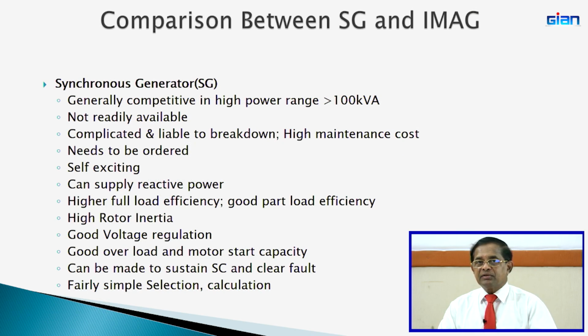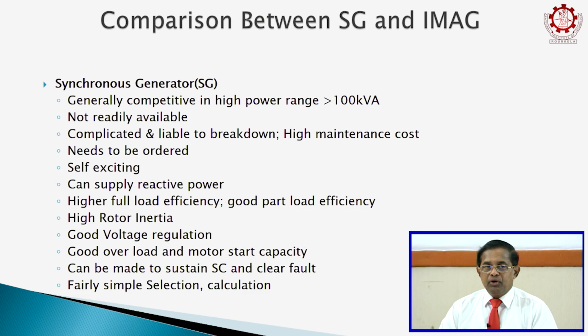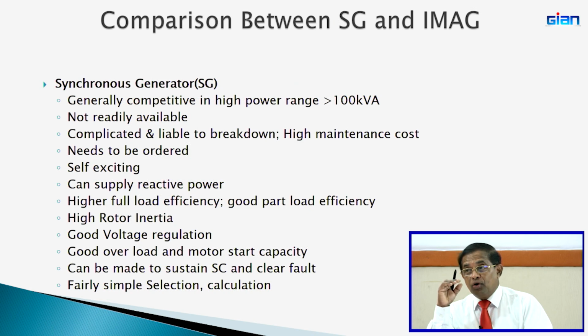Usually mini hydros are not contractually expected to provide reactive power to the utility. For large private power plants, yes, there is a contractual obligation in the power purchase agreement, when requested by the utility the owner should provide reactive power, right. But for small hydropower plants and small other solar and so on, there is no mandatory requirement to provide reactive power, although the synchronous generators can provide the reactive power. Therefore, small hydropower plant owners usually try to operate the power plant at unity power factor.